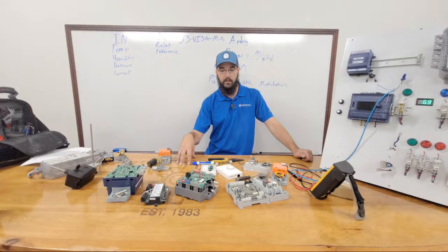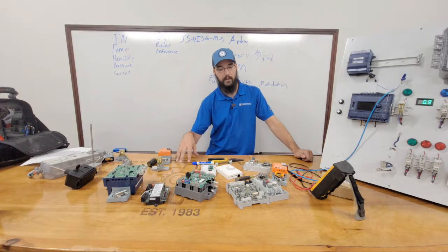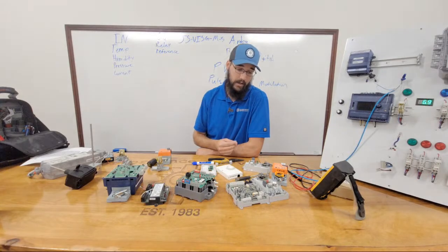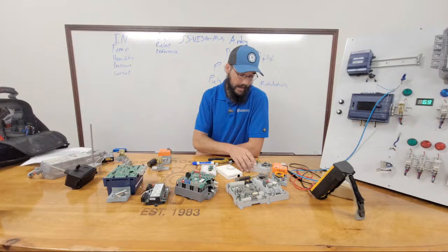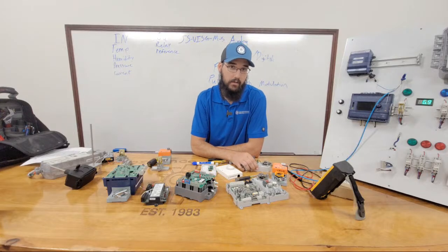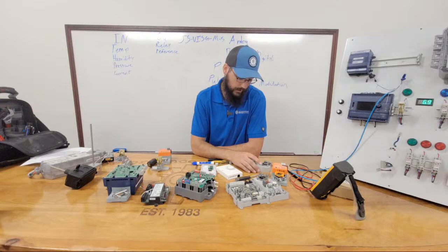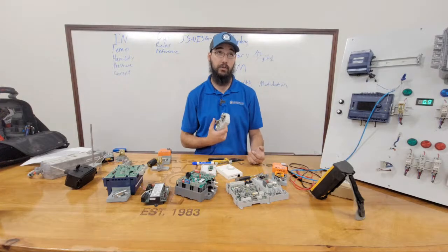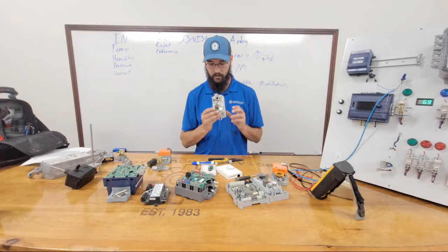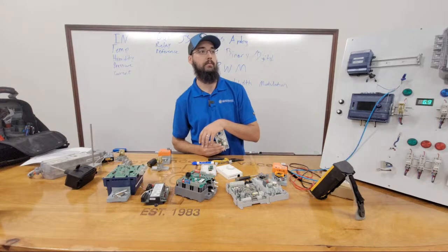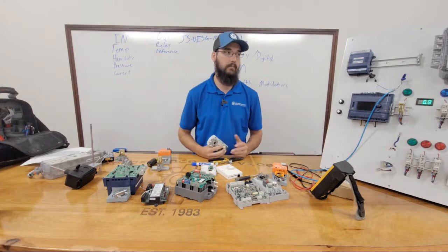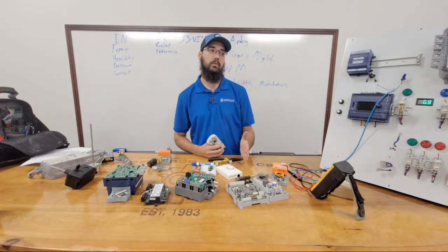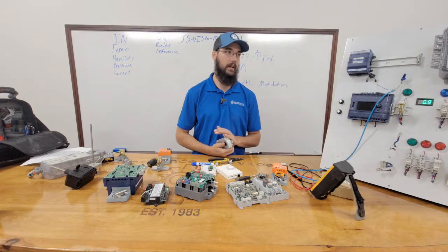So you will walk up to some where that feature is not built into the logic of these controllers. In that particular case, the only option you have is to do it manually. So there's two ways of doing it. If you already know, okay, I'm supposed to be at 100% and I want to calibrate this thing, then just hit your clutch, drive it to what should be 100%, and then see if the automation system will react in such a way and begin to close it back down.